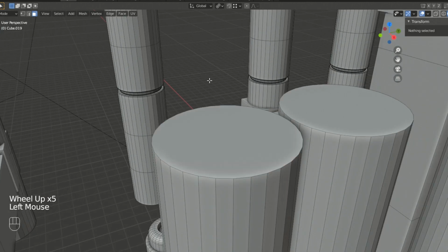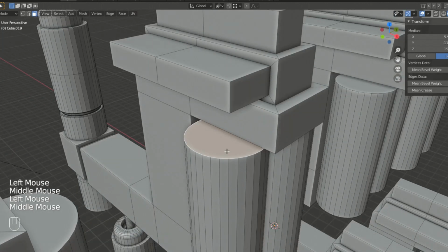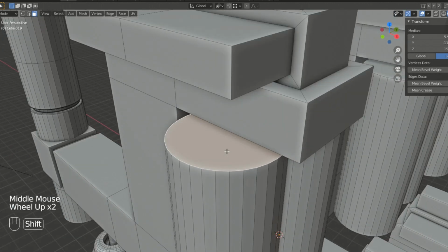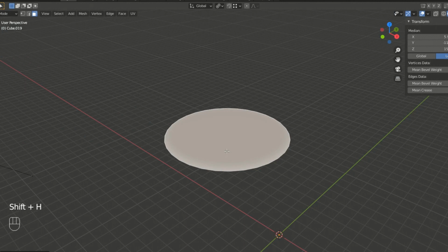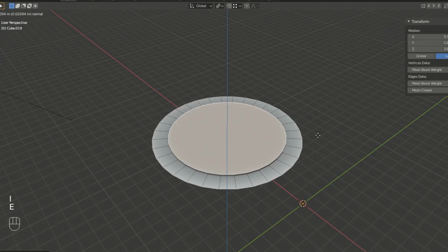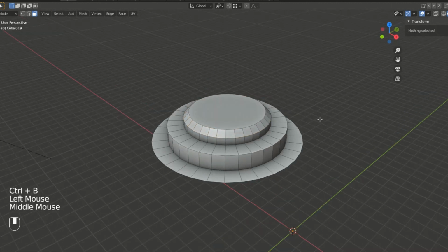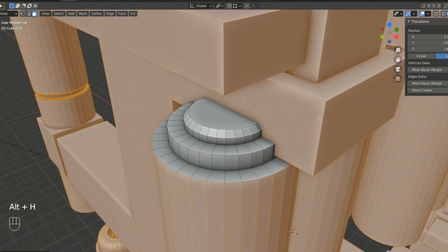So how can we do that? I can select this face and then press Shift H. Using Shift H, everything else will be hidden. And I can concentrate on this. I, extrude, I, extrude, and then Control P to backfill. Okay, finished. Then I can exit by pressing Alt H to show everything again.